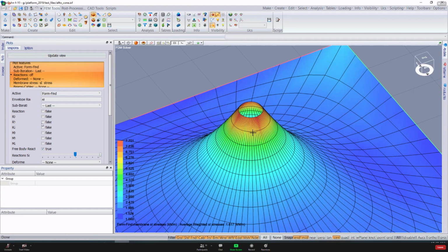Let's give a look. We have 10 minutes left. Maybe, Jerry, we can add one more aspect related to this question. You predefined the square boundary and you predefined the central ring. And then you generated the mesh in between, and then you pretensioned the whole thing. If you would do that with the soap film, as you explained earlier, the soap film would not work here because the ring in the center is too small. Exactly, the soap film would just pop off.